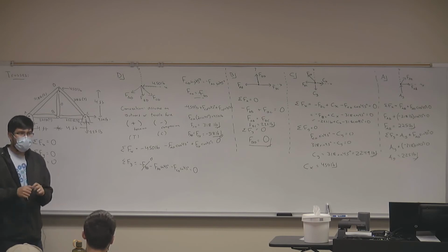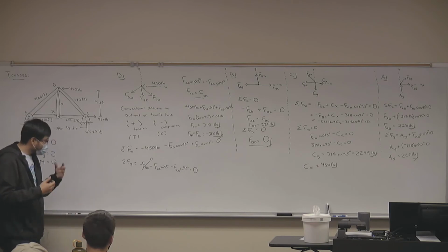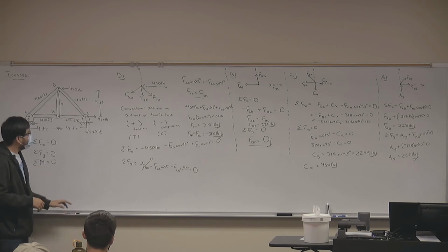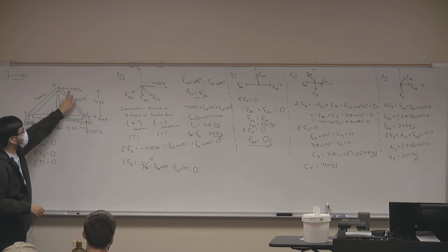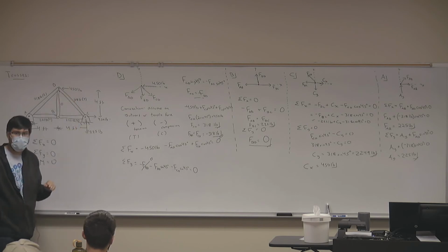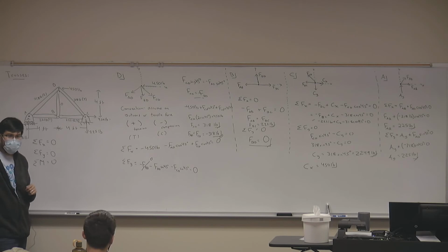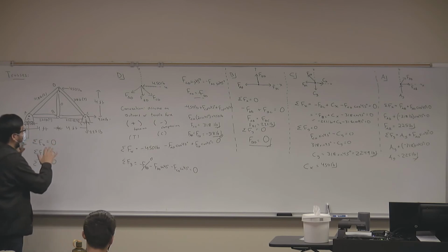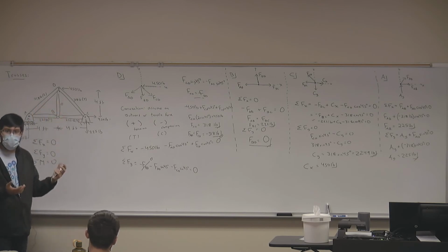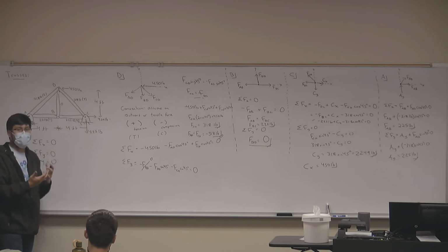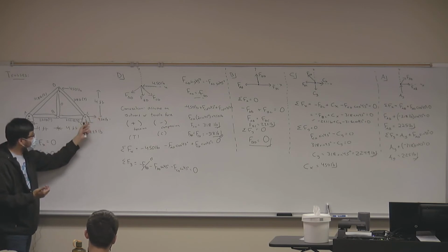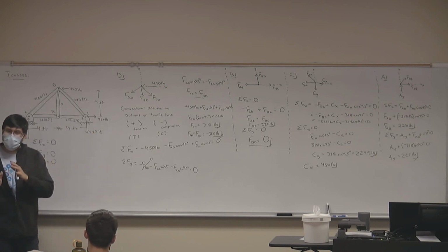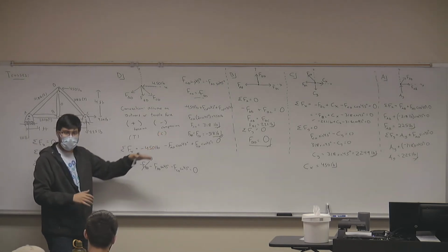Any other questions? I have more of a conceptual thing, just from statics. Does it make sense that this C is actually the same magnitude as this force, but in the opposite direction? It does. Why? It's the only reactionary force in the x direction. Exactly. So remember when I mentioned earlier to look at these not just as individual bodies within a structure, but to look at it as one structure, because we can actually find these reaction forces before having to go through this process. Now, notice that it's not necessary because we found them anyway, but it's still possible.